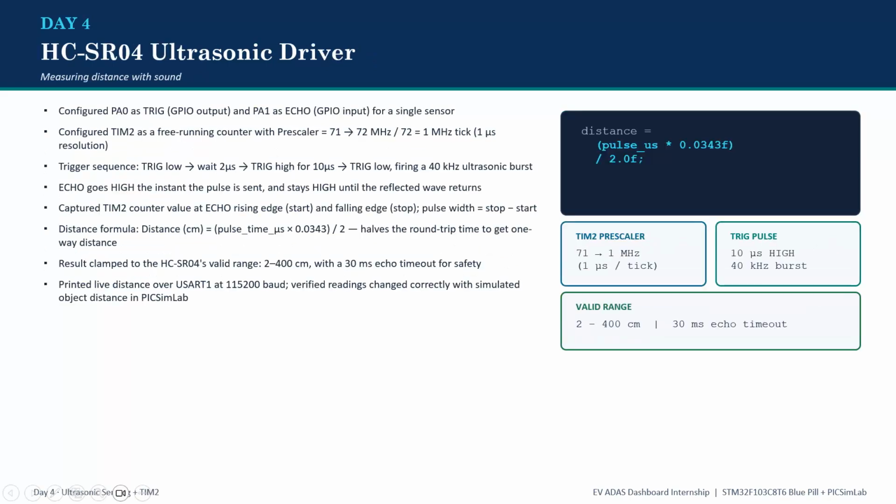On day 4, we moved into distance sensing with a single HC-SR04 ultrasonic sensor. I configured PA0 as the trigger pin, a GPIO output, and PA1 as the echo pin, a GPIO input.